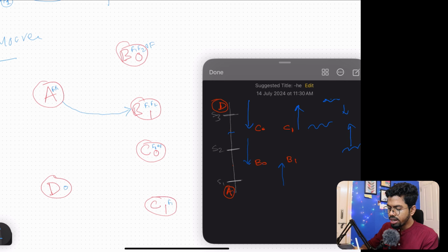And when I am at A, all three of my sensors are down, but anytime one of the sensors comes alive, I'm sure I'll reach B1, because B1 implies you are going from the down water level to the top water level, and A is my down water level, and B1 is a top water level. So that is perfect. Now anytime you are at A and your water level increases slightly, but you haven't reached S1, S1 is not set, you are still at 0 0 0, so that time I'll be at state 1. So 0 0 0.